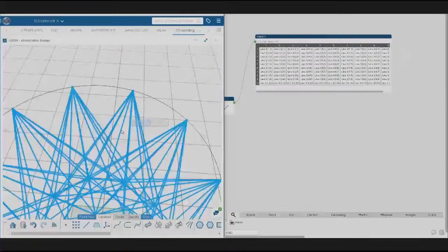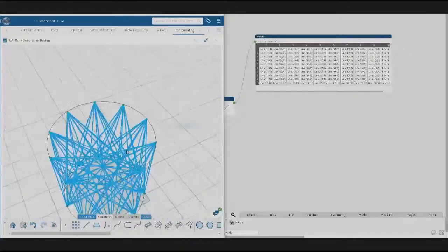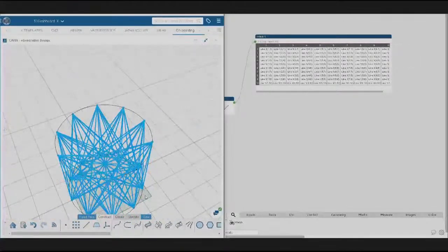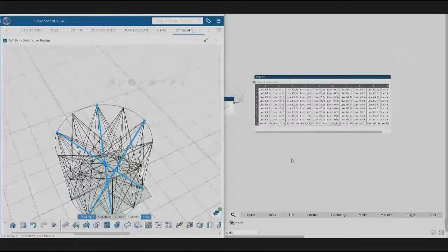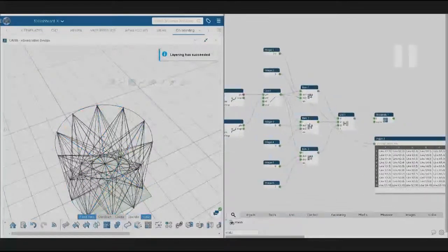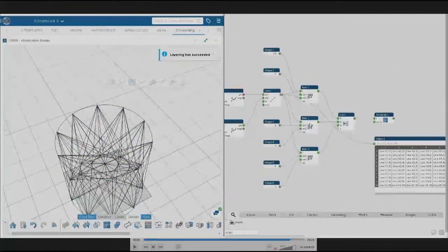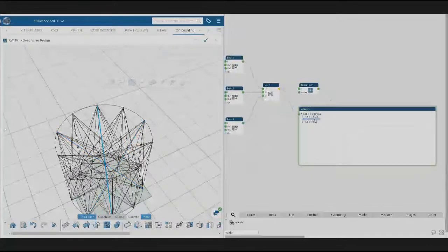So here I'm actually going to isolate different elements one by one. Different elements on different lists have nothing to do with each other, but I need to extract them for some reason, because you have a lot of exceptions in parametric design. So here I'm going to create an assembly, and you can see that it created the sublist in order to extract those lines. Out of those lines it created a sublist with the right indexes in the first and second dimension. So this is absolutely key in parametric design, working with lists.